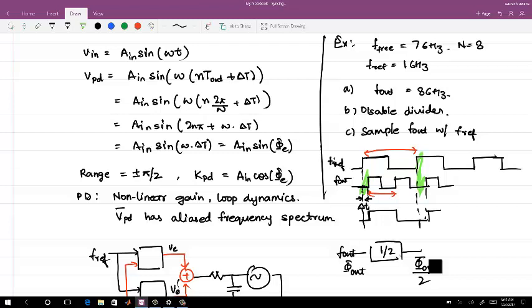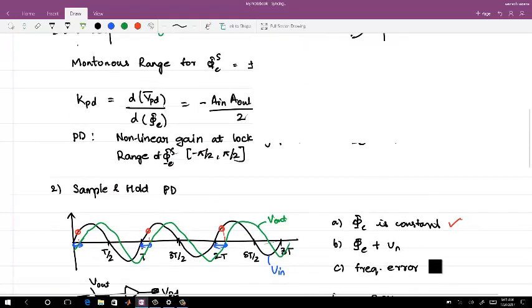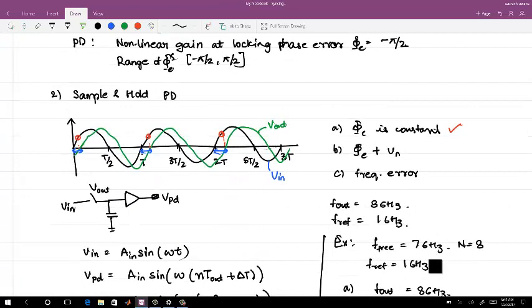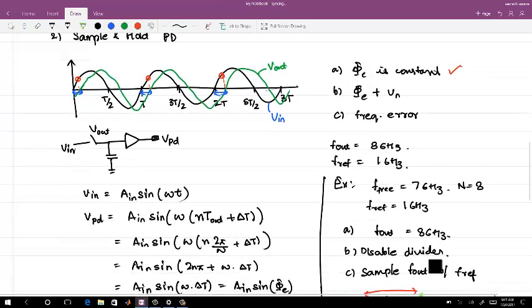Whereas this sample and hold circuit is like a simple, single switch. Here also it will depend what kind of amplifier I am using in between. What linearity does it have? At least from an energy point of view, what I see these days is that sample and hold phase error detectors are quite good. They will surely have a drawback: this can't do the same even if the frequency drifts. If the frequency drifts, you need to have a separate loop to correct for that.